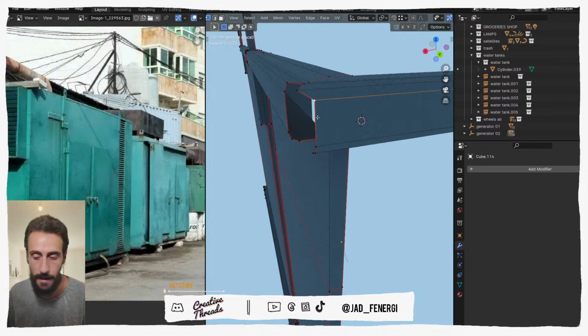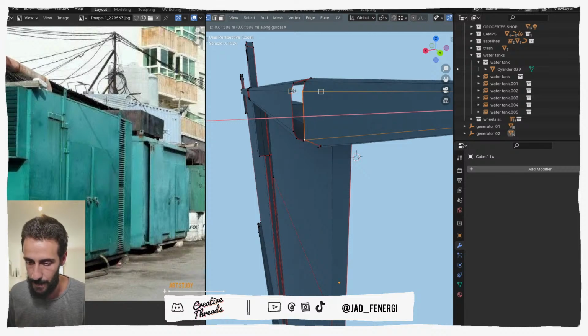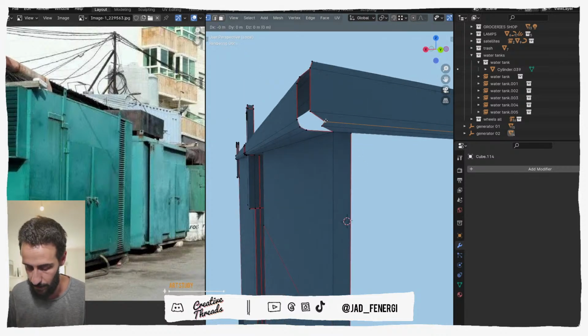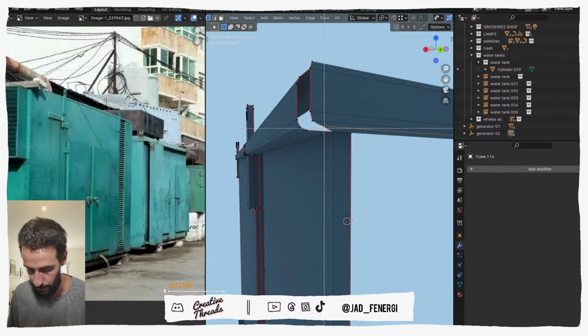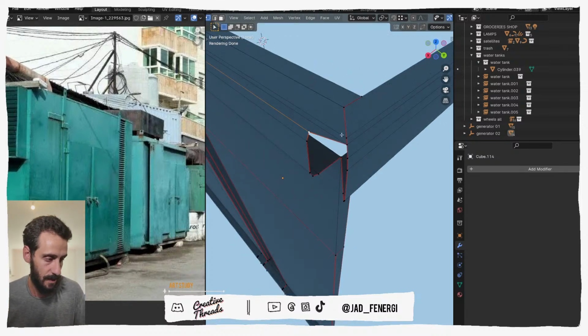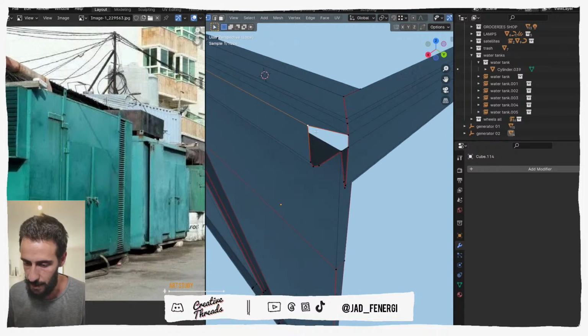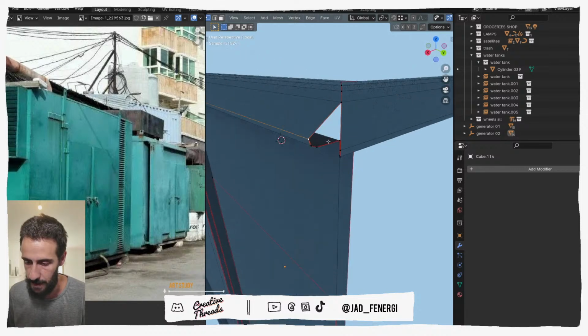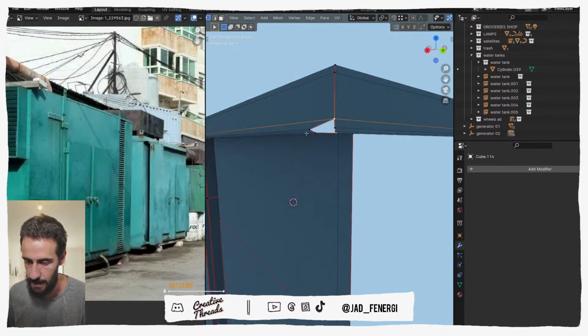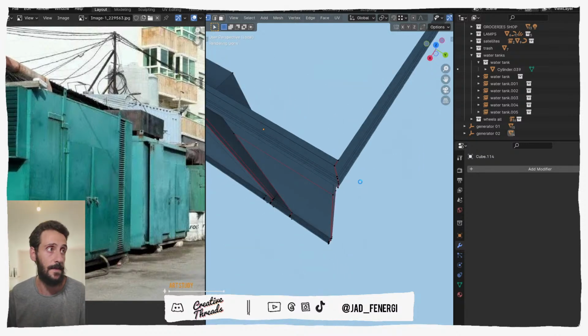This is the thing with Blender is that you can do things in many different ways. There are much faster ways than doing like what I'm doing now. But sometimes your brain will just refuse to figure out the solutions, the best optimized solutions. So you just go on with the best solutions that you have at hand right now. So Shift R is repeating the last command. So by selecting now, I can just Shift R, and now we have this at 45 degrees.